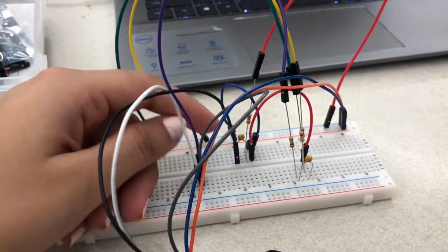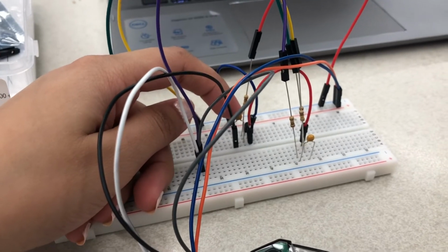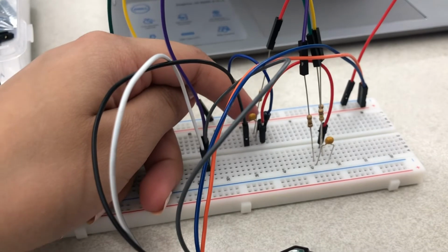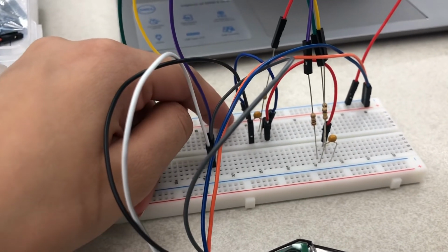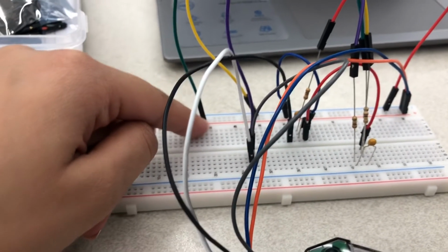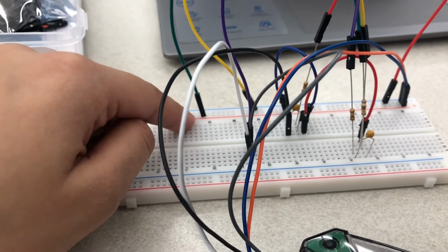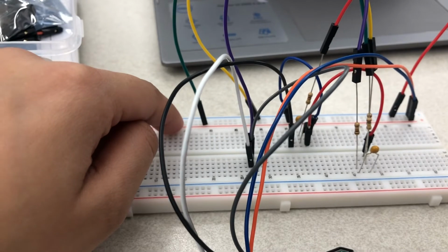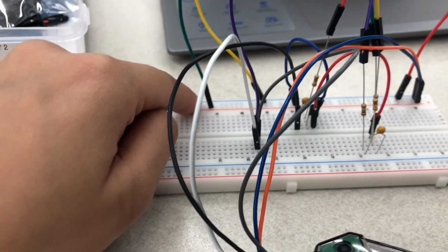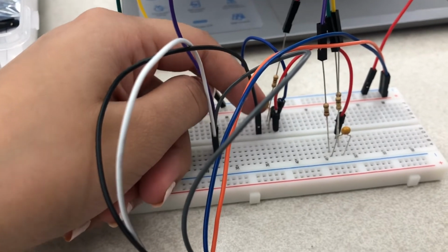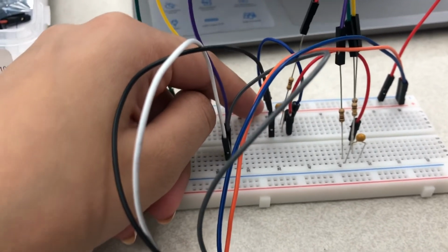In my circuit, the BJT is placed exactly in the center right here. From there, the collector, which is right here on this side, is connected straight to this positive line, which will all end up merging together and go into positive 5 volts. The negative line on the other side will all gather together and go to negative 5 volts. So the collector end goes from here all the way to the positive 5 volts.